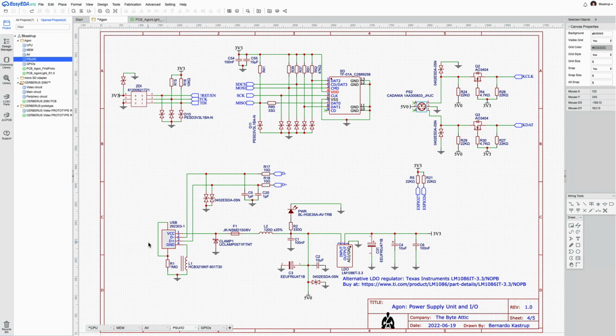And a cable, even if it's insulated, there are variations. There is interference involved. And what could happen is that the ground level of the transmitter, your PC that you connect to the USB port, that ground level through the cable may fluctuate. And if it fluctuates, then the reference for the D plus and D minus signal will change.